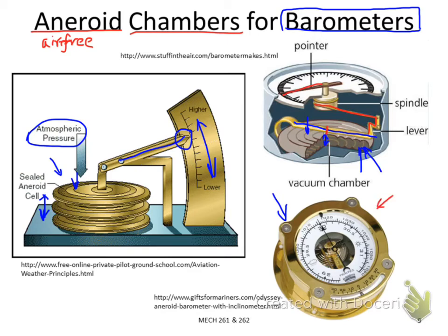And this is a photo of this device. So this is schematic, this is a photo. It is actually a practical altimeter. You can see the aneroid chamber is inside here, and this indicator indicates the height or the altitude difference. This is still the device all aircraft are using to measure altitude, because this device is nearly 100% reliable. It's more reliable than electronic altimeters. For aircraft you always want to have a double reliability design, so usually this will be the final one to measure the altitude.